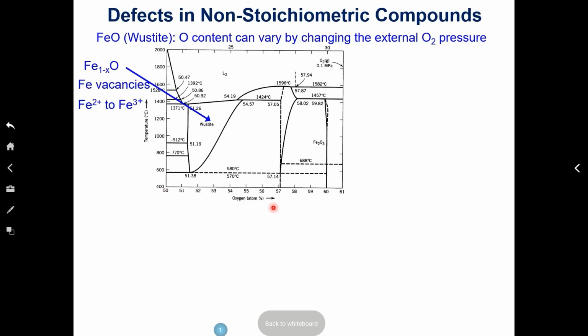So this is the iron-oxygen binary phase diagram. And you can see this is the wüstite phase stability range. And there's a huge oxygen non-stoichiometry, depending on the oxygen partial pressure PO2, that you can control to create different levels of Fe1-xO. So you can see that range, depending on the temperature, is bigger the higher the temperature. So there's quite a bit of window. You can tune your x simply, and the tuning knob is your PO2.